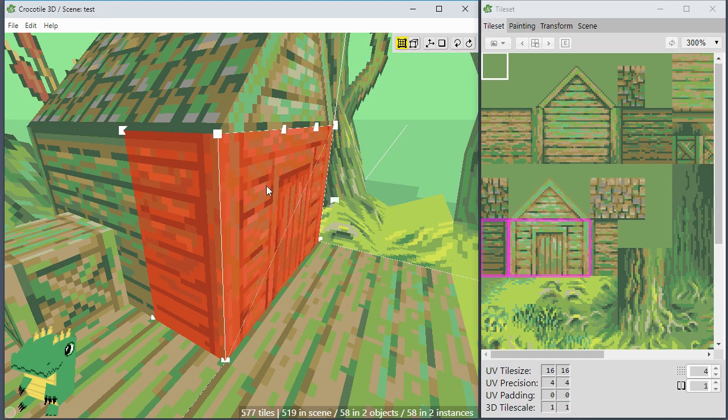Whereas if you select the smooth vertex normals, it will attempt to average the vertex normals with neighboring polygons, neighboring tiles. So this edge between these two would get blended together, and the vertex normals work with lighting and rendering.